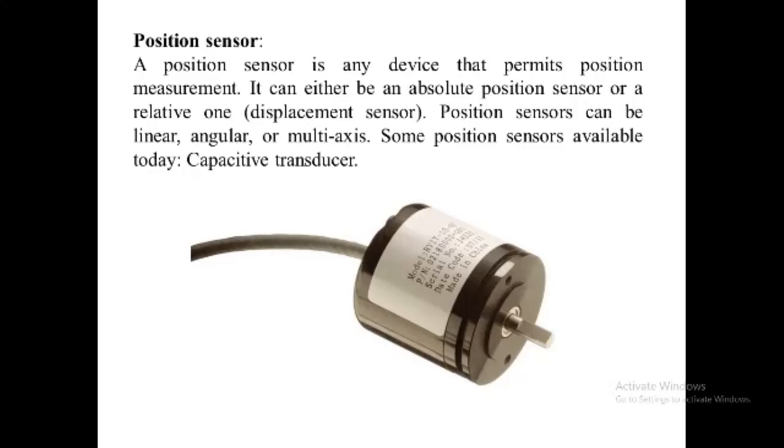Potentiometers come in a wide range of designs and sizes, such as the commonly available round rotational type or the longer and flat linear slider type. When used as a positional sensor, the movable object is connected directly to the shaft or slider of the potentiometer, and a DC reference voltage is applied across the two outer fixed connections, forming the resistive element.